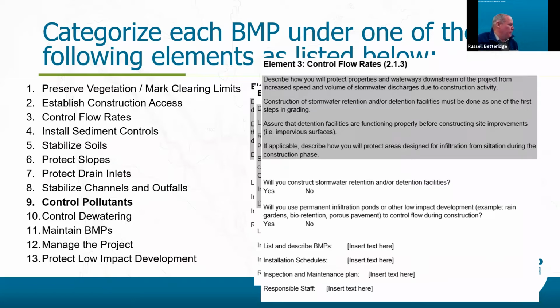But the SWP template is really good because it walks you through that thinking. And if you don't just skim over it and pass by it, and you really put some thought to it, like assure that detention facilities are functioning properly before constructing your site improvements and putting down impervious surfaces. Don't get that horse behind the cart, right? Make sure you're doing that in the right order.